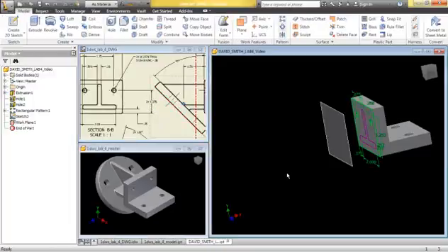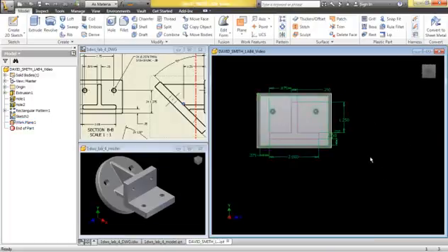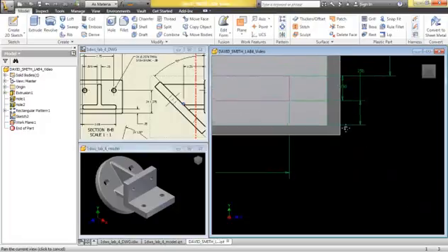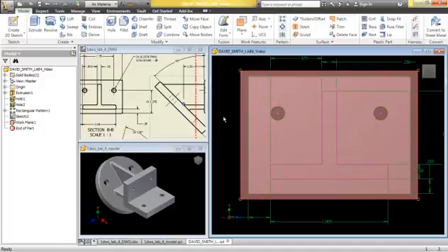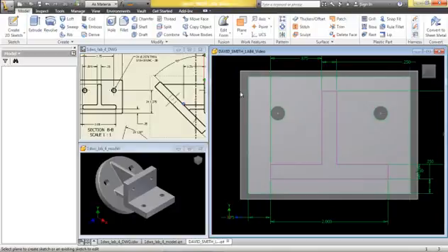So then we'll look at that straight in. I can click on the plane, right click, and do a look at, or I could hit the page up key, and I'm looking straight in on that now. So now I need to project a little geometry. I had to get a sketch plane first, so I'll go 2D sketch and grab this work plane. Make sure you grab it on the edge of the work plane. If you go to grab towards the center, notice it's highlighting the other face. I want this work plane right here.